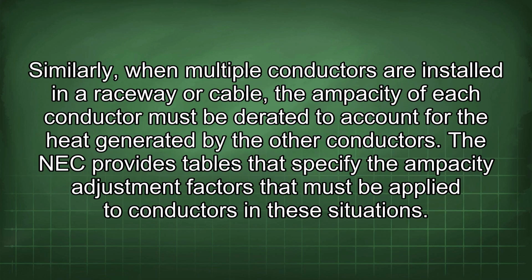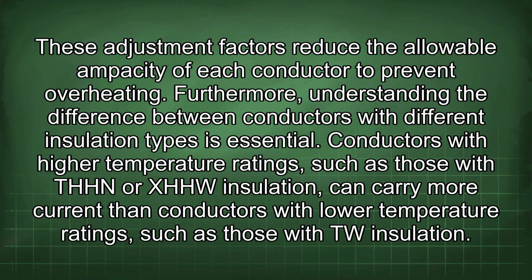fire. Similarly, when multiple conductors are installed in a raceway or cable, the ampacity of each conductor must be derated to account for the heat generated by the other conductors. The NEC provides tables that specify the ampacity adjustment factors that must be applied to conductors in these situations. These adjustment factors reduce the allowable ampacity of each conductor to prevent overheating.